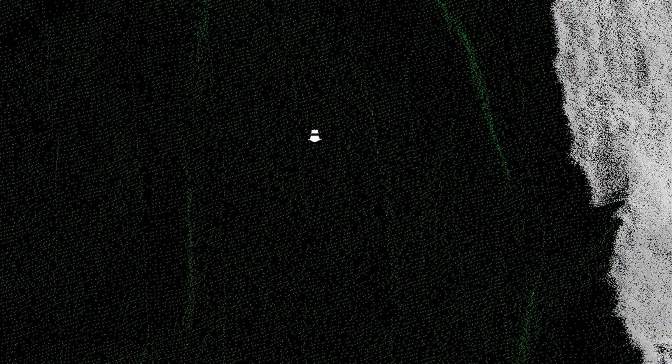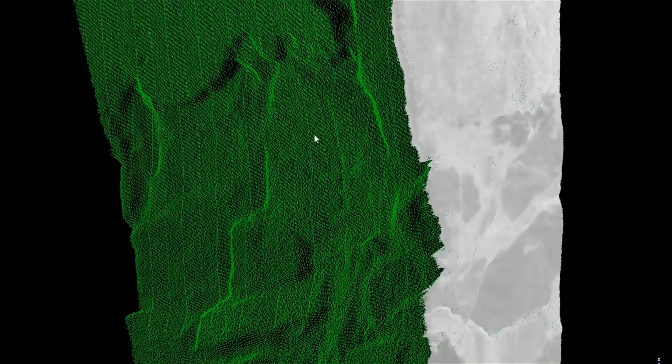So you may in fact spend the same amount of time at a position if you're just capturing a small area. Now, if we look a little bit closer at the details between the two different scanners, if I zoom in on the data from the TX8, you'll see I'm zooming in at the black writing on this sign. You can see a lot of detail in that. If I zoom in on a similar area with the SX10, you can see that you start to get spaces between the points very quickly.